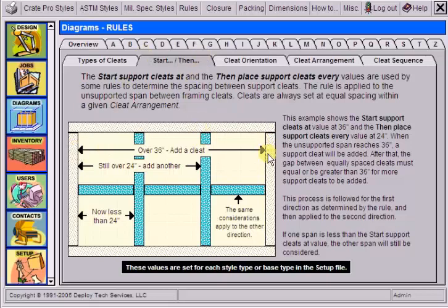As I mentioned, there's also rules that work on the size of the plywood. Let's assume that this is an inside framed panel. And quite often on a panel that's framed on the inside, you may have the plywood actually hanging outside of the cleating. They don't go to the edge. Now, in this case, our plywood would start here, and a rule that may have been applied would be on seam only.